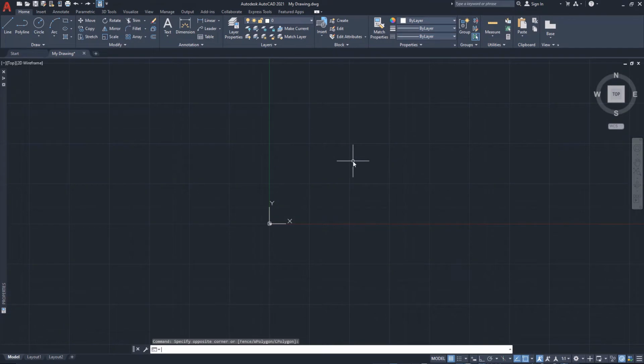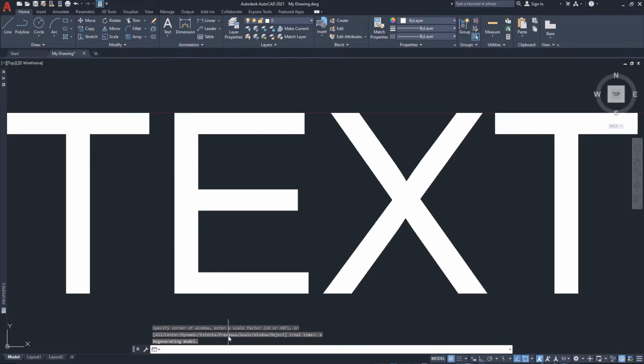Once you have saved the text change and exited the Mtext command, type Z and Enter to initiate the zoom command, and then E for extents and hit the Enter key. Provided all other drawing elements were successfully erased earlier, the user's display should zoom in on the newly created text object.